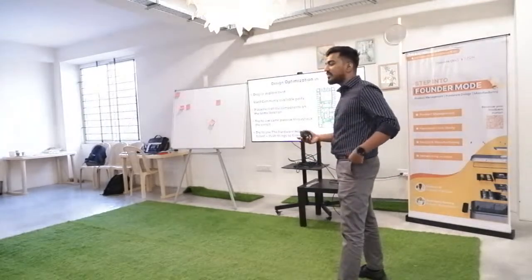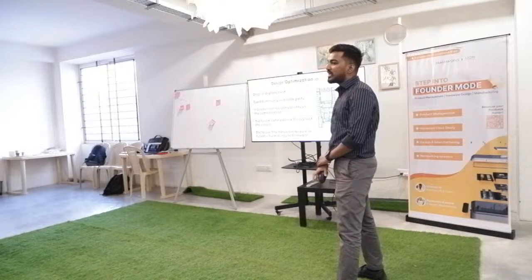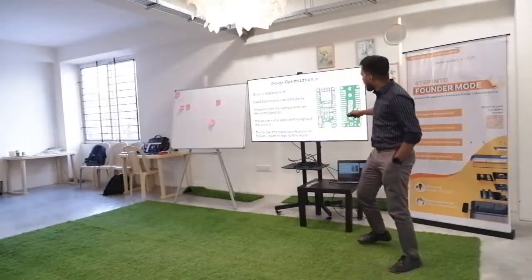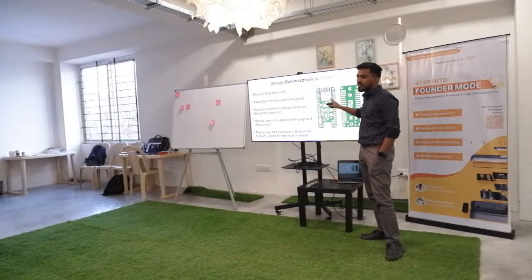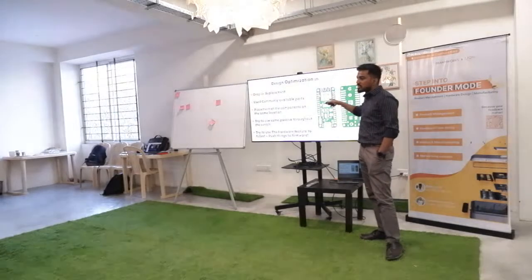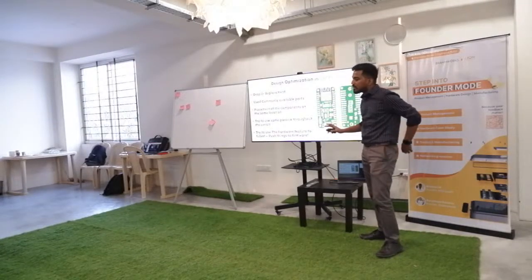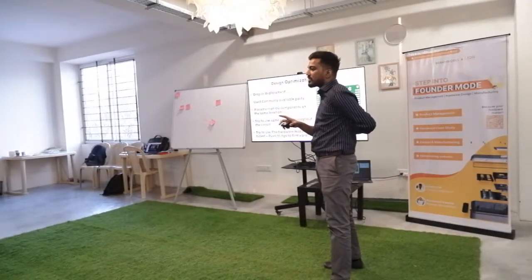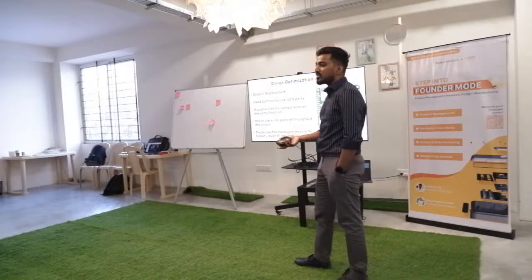This might not be very specific to your design, but it's very specific to our design, what we have done here. As I told in the beginning, it's one design, 3 different products. So here, 80%, or 100%, none of the components will move. Even though there is a different routing for each of the boards to match specific numbers, 100% of the time, the components will remain in the same position. The advantage of this is we have to make only one single stencil. We don't have to make more stencils, and it also reduces our cost in terms of R&D.